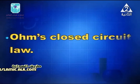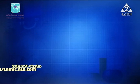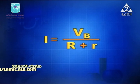And what about the relation that expresses Ohm's closed circuit law? Ohm's law for a closed circuit. Okay, it's all easy for you. The current passing through the circuit, current through the battery, I, equals V battery over R capital plus R small. So, once again, current through the battery equals V_B over R capital plus R small, R total of the circuit. This is the expression that gives Ohm's law of a closed circuit.